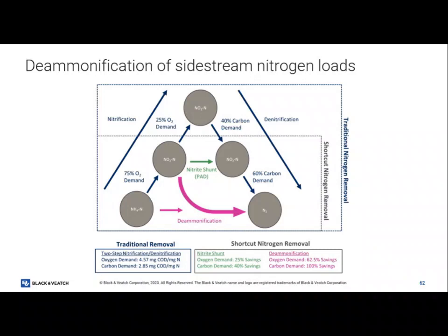It sounds complex, but these bacteria, once they grow, the slow growing bacteria, remember I said use very low ATP, but slow, here's a general rule of thumb. Slow growing, slow dying. Quick growing, quick dying. So they don't die quickly at all. Their death rate is very, very low. And in fact, when they first brought them over to the US, the first plant that brought them over, they were almost dried. And you just throw them in the water and they basically hydrate again and come back.